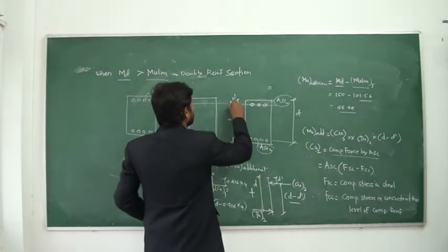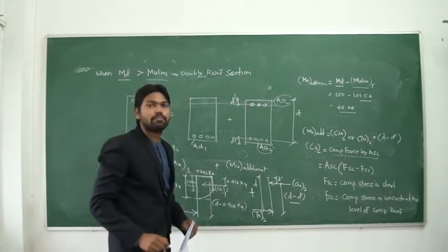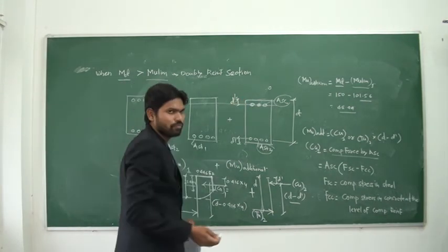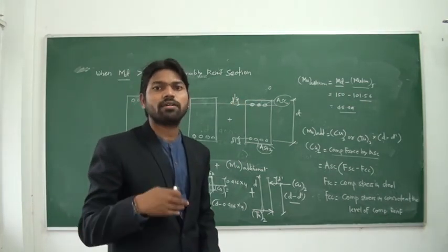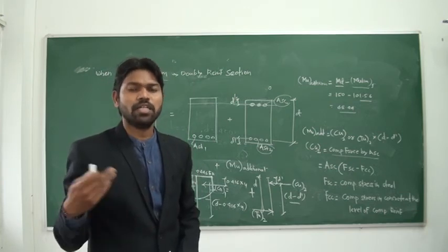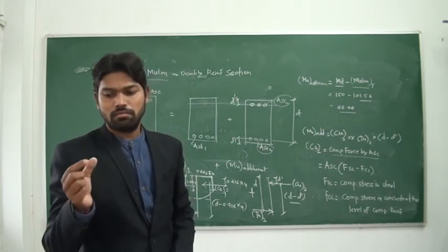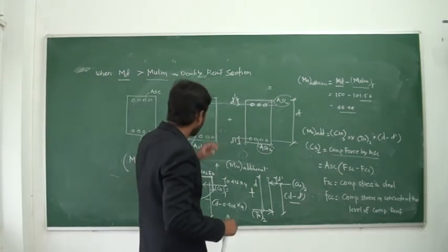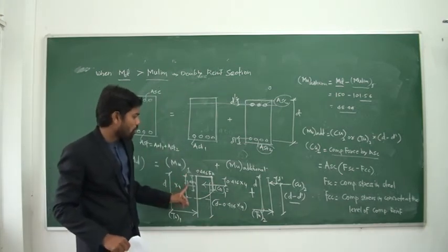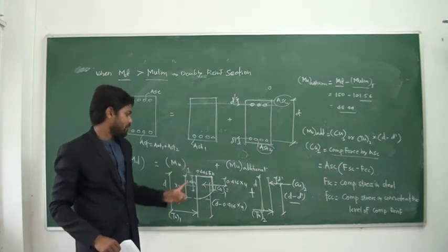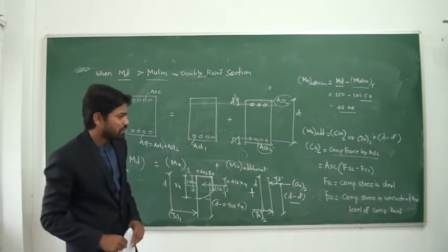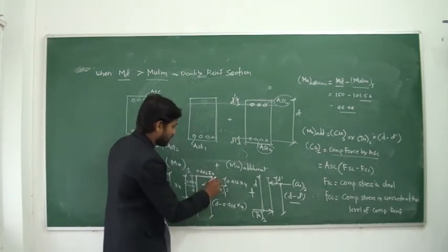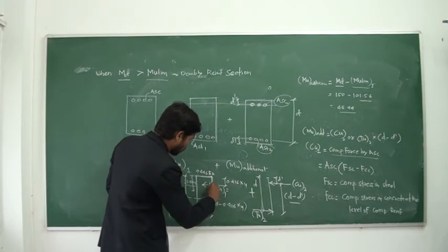It means at a depth d dash, and d dash is an effective cover. It generally varies from 30 mm to 50 mm. The effective cover varies depending upon the exposure condition and the diameter of reinforcement. The d dash value is generally less than 0.43 XU. So the level of reinforcement lies within this constant range.